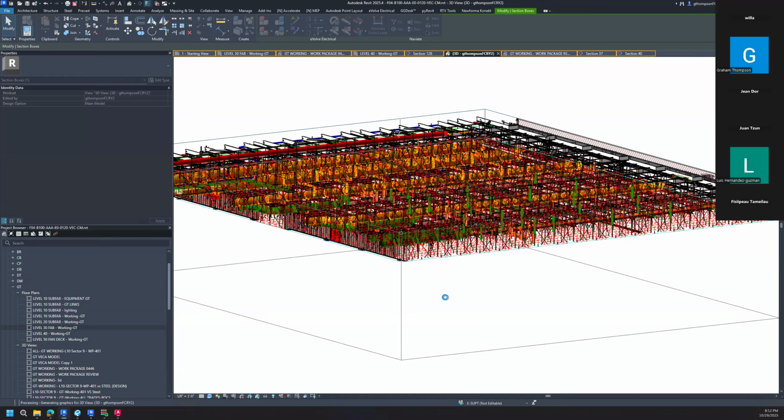A point cloud is, and if you take my BIM class, you'll learn all about this too. That's one of our BIM focuses. A point cloud is a scan. You go in and you scan it, and it's going to be important to have a point cloud later because we have to provide a document that matches within an eighth of an inch of the scan document. We may have to go back and update locations if they put them slightly different in the field.